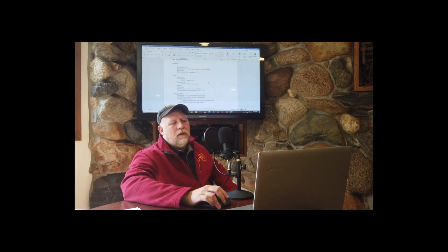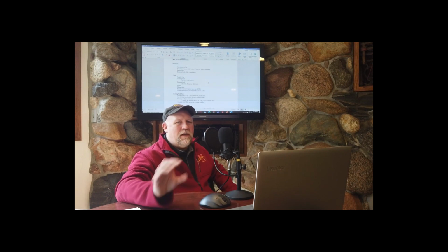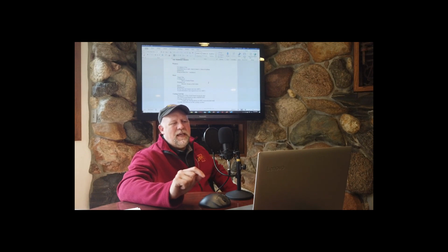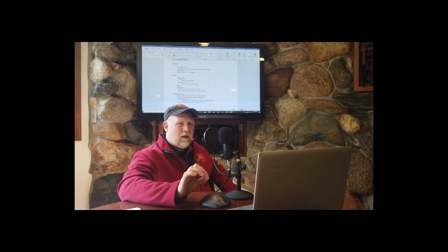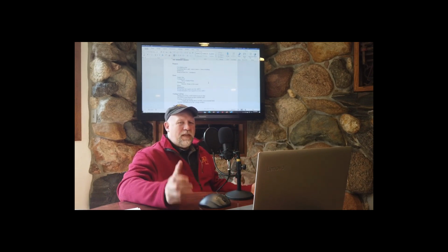Basic parts. You've got to have a supply fan. The supply fan is what's going to push that air down the ductwork and into each room. Right? So a supply fan is a key component. A cooling coil, another key component. The cooling coil is what removes energy from that air. Remember, we calculated this in the first part of this class. We calculated, well, what is the cooling load? Well, physically, something has to cool that air down and dehumidify it, and that's the cooling coil.